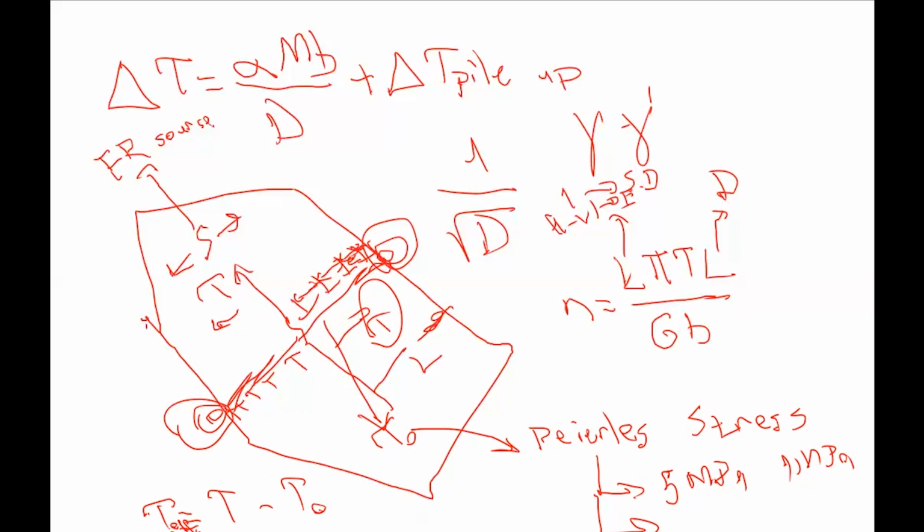The stress to make a dislocation move is the applied stress minus the lattice resistance. And since dislocation motion is impeded by grain boundaries, dislocations will pile up at the grain boundaries until the stress is large enough for them to break the grain boundaries and pass to another grain.